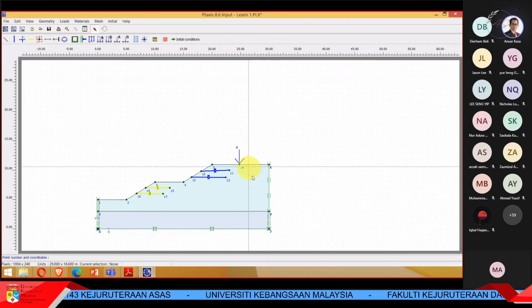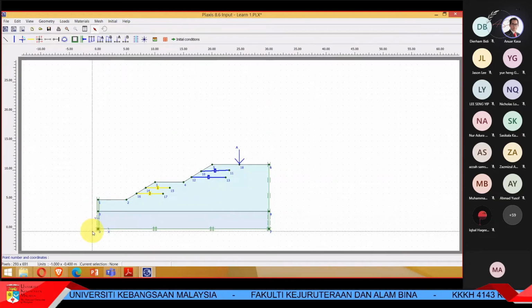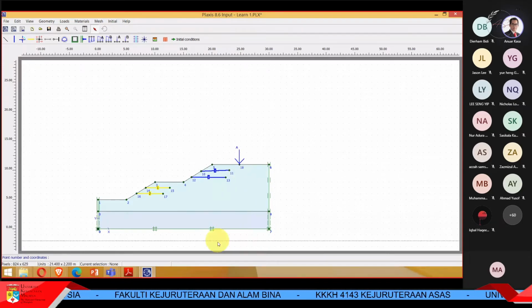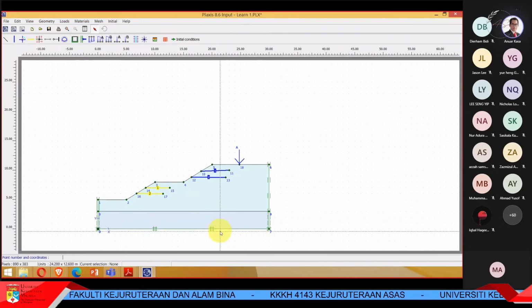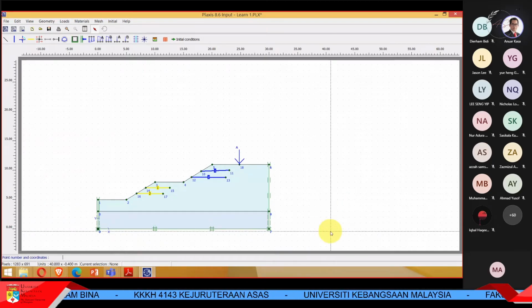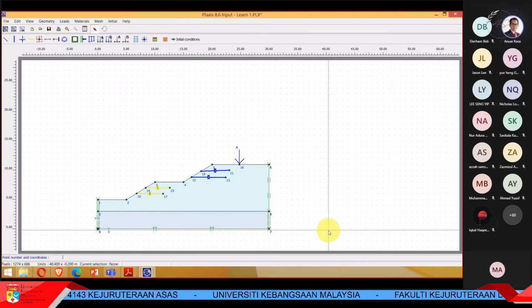Don't do the full analysis manually. Especially, this one is not for that. For SLOPE/W, you still can do manual calculation, but for Flux, maybe you can calculate the stress because it is an easy calculation. What is the stress at the bottom here, the highest? You can calculate easily, and then you check that Flux gives more or less the same. That is one way to check. Or maybe the groundwater level is here.